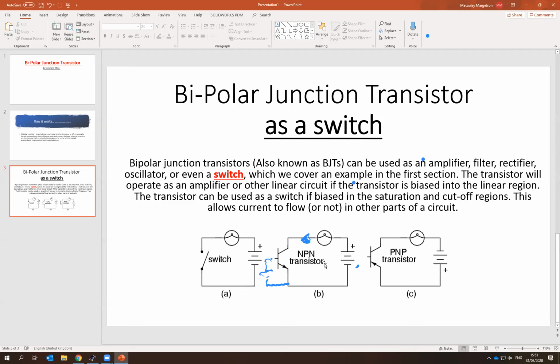So if you think of a mechanical relay that you'd probably have experienced at work, where you've got a coil and you use that to switch motors and things off and on, if you use a transistorized output as a switch, you're talking very much quicker response times. The other thing is you haven't got that mechanical wear that you've got in a relay, because a solid state device is not going to wear out mechanically.